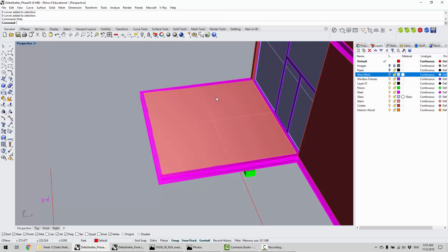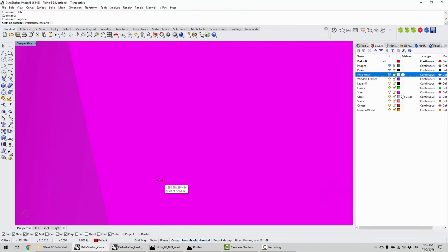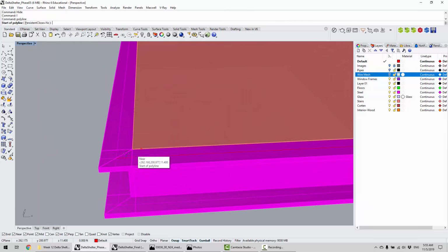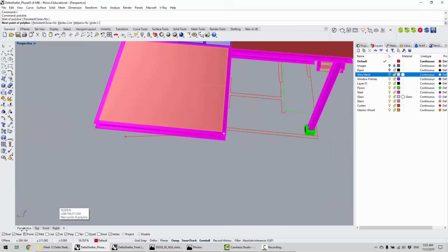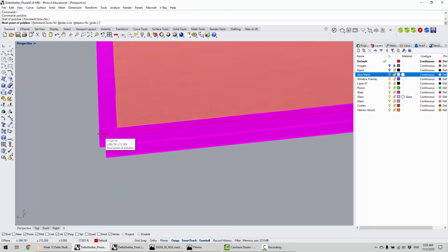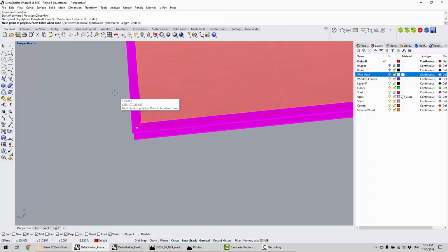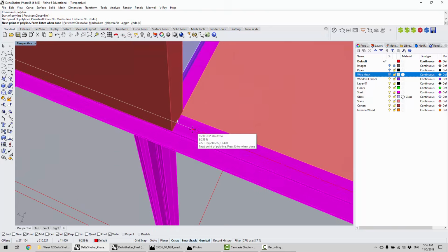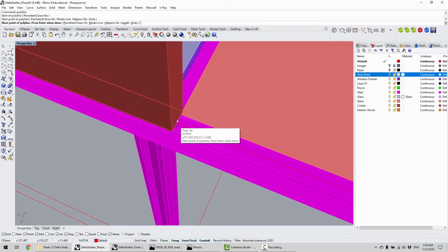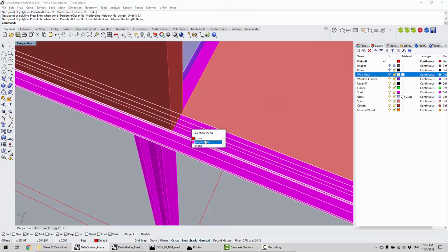Just using the polyline, right? Oftentimes these will give you something that you can snap to, especially at these corner joints. So this guarantees that it's at the center. Let me turn off my mirror because it's freaking out. So that's right, and you can go here. What I would say is don't go all the way to the end, because then your pipe will be half embedded in the wall. Pull it slightly short and find a dimension that makes sense. So here, maybe it's 9.4, right? So there's a little bit of room between the ends, okay?